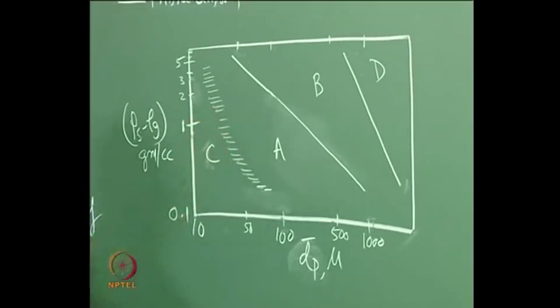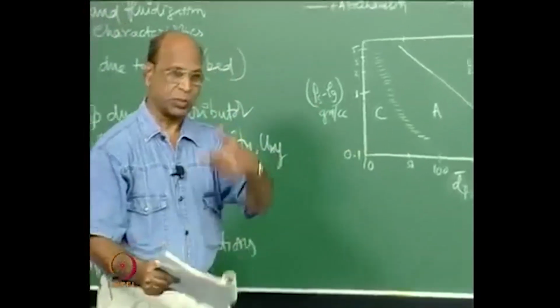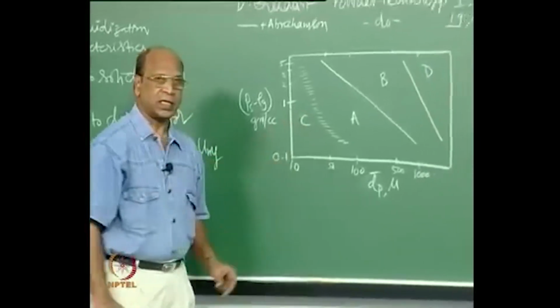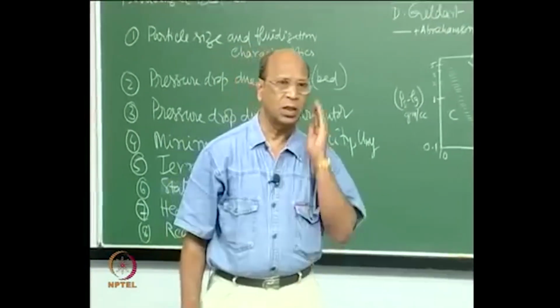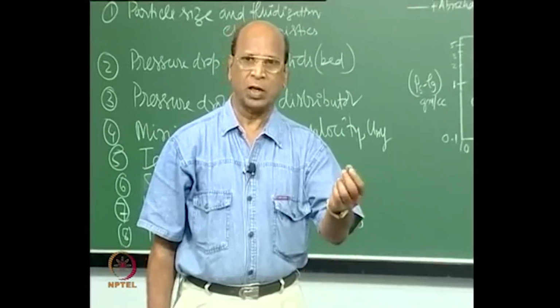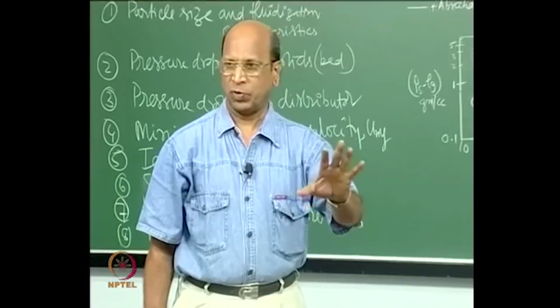I think they put all the data and then try to interpret, but I will also give you some sizes later. But generally when you have small particles, you have cohesive powders. One example is talcum powder, what you put every day morning. Okay. I mean, if you have talcum powder it will be around 1 micron, 10 microns, I mean less than that, a very fine powder.